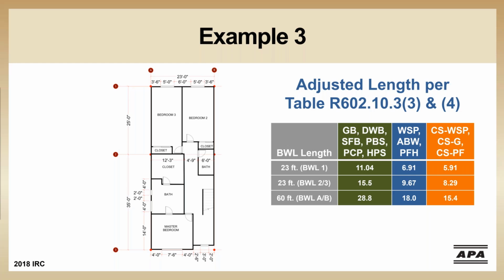When we apply the weight and spacing adjustments, all the required braced wall lengths will get the top floor weight adjustment of 1.2, but only the middle row in the slide above is getting the braced wall line spacing adjustment of 1.4. After adjustment factors are applied, we establish the required total length of braced wall needed for our project.